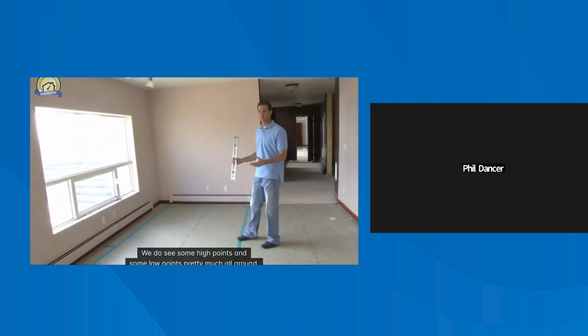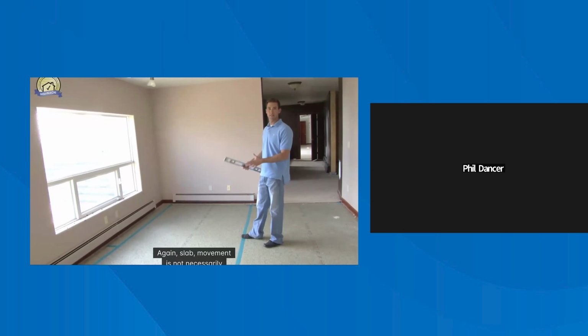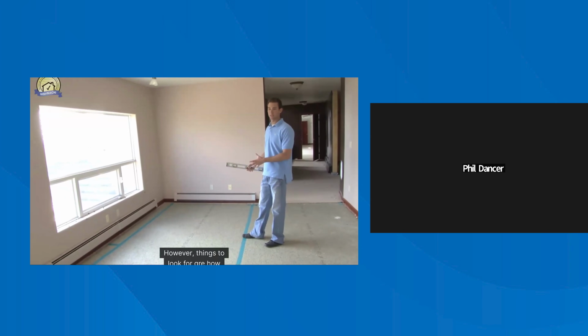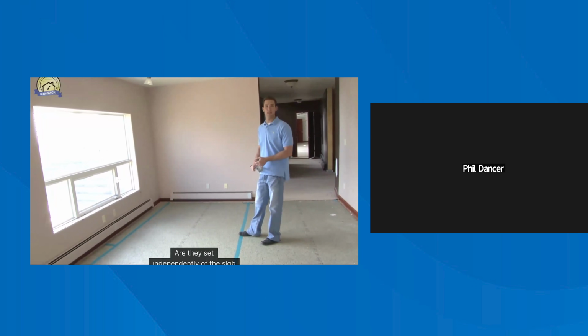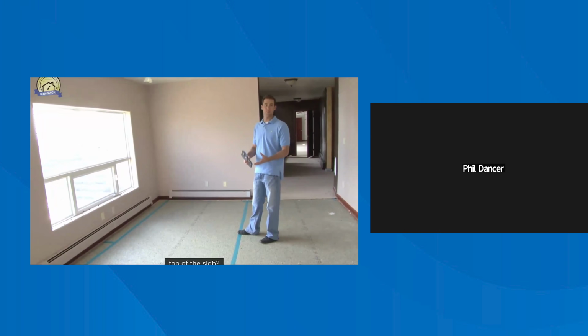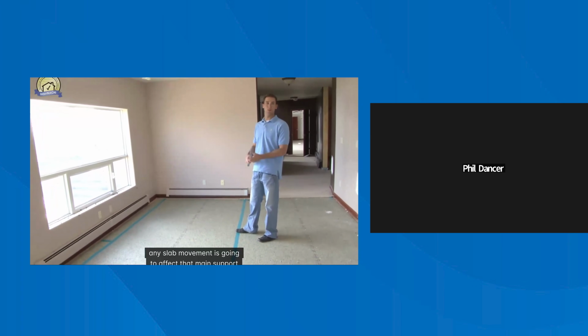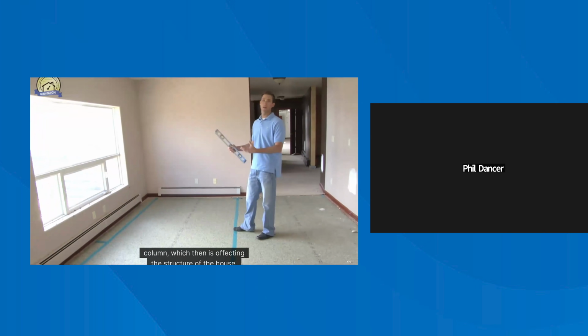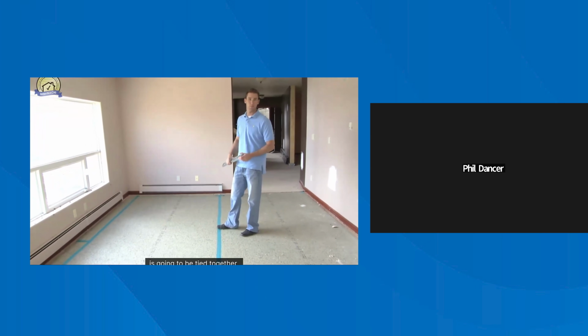We do see some high points and some low points pretty much all around. Again, slab movement is not necessarily indicative of structural issues. However, things to look for are, how are the support columns set? Are they set independently of the slab on their own foundation, or are they just set on top of the slab? If they're set on top of the slab, any slab movement is going to affect that main support column, which then is affecting the structure of the house, affecting the main beam, and affecting the floors above, because everything is lineal, everything is going to be tied together.